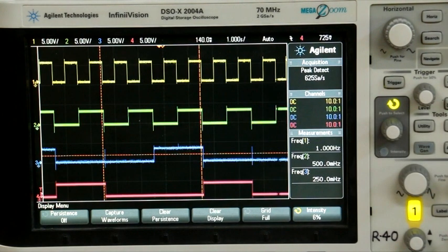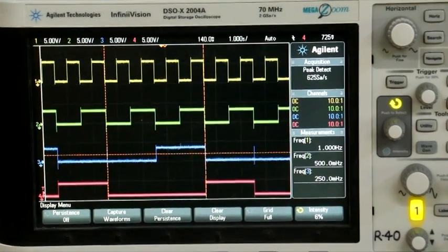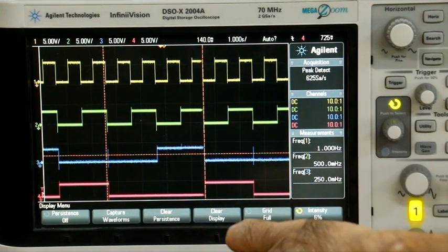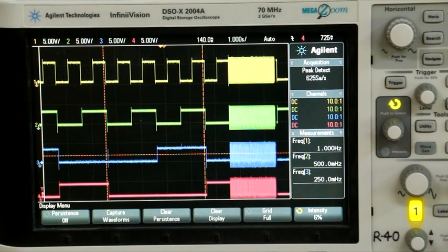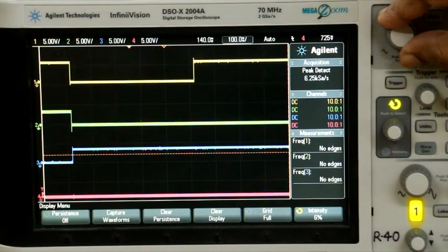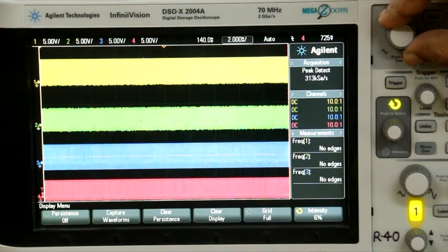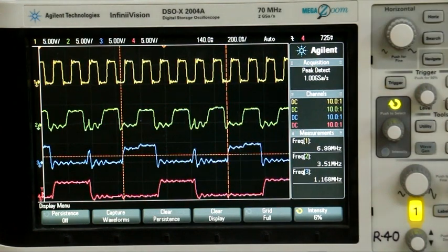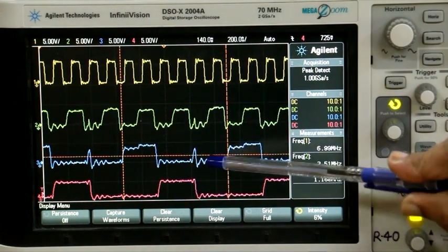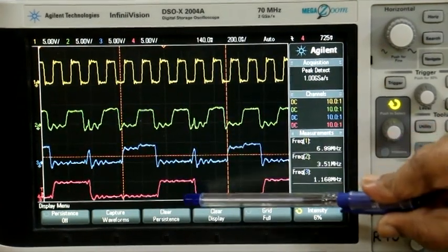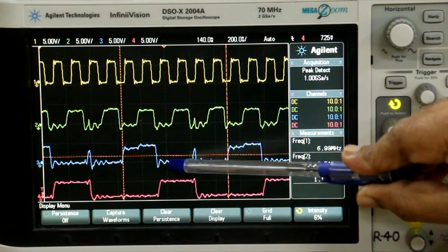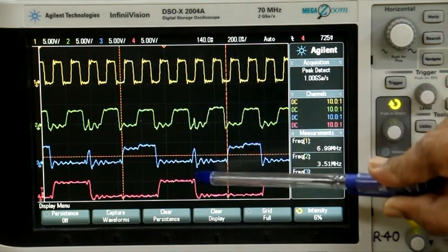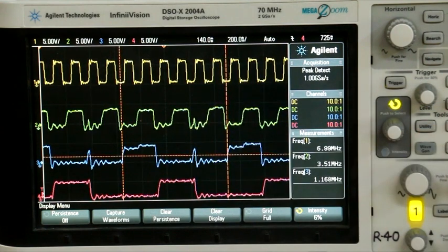What I want to show now is, let me increase the frequency. Right now it's 1 Hertz. Let me make the frequency 1 megahertz, and let's see what we would see. Yeah, so right now the frequency is 1 megahertz, and now you are able to see this particular B output going high. So you can see once again same thing. So 1, 0, 1, which is state 5, and as soon as the B output goes to 1, 1, 0, you can see it went up and came down for a very short time.